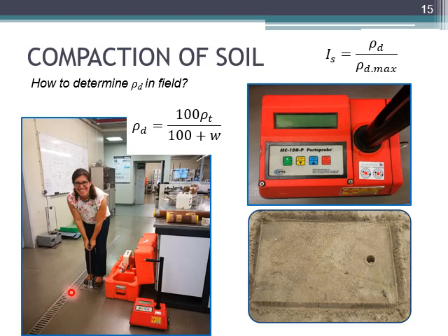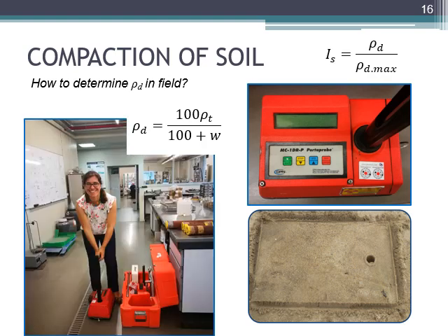Of course, she's showing that on the floor. That should be done in field, but well, this is where she was able to show that to me and to you. Okay, so first you locate a template, and then in the same place you put the equipment. And you can simply read the value of the water content from the screen. So the method is really fast.